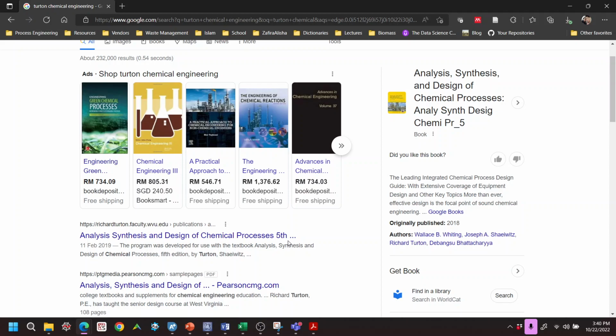So maybe you can simply escape by using the conversion reactor, and then use the distillation column. So that at least we have the reactor and distillation column, and then you can do whatever you want. You can assume that conversion is one of your independent variables, and that conversion obviously depends on the temperature, which you may or may not have, but it's something you have to think about.